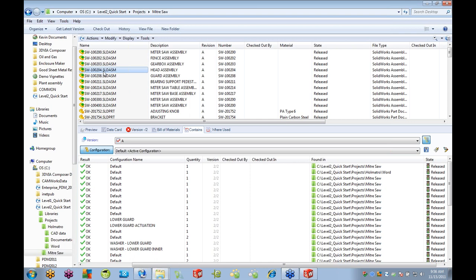Okay. What if you created it on the C drive of the server? If you created your local view on the C drive of the server, you're not going to gain any of the benefits of eliminating that check-in, check-out across the network, because when you check it out, it's just going to move it to the C drive of the server. But when you open it in SolidWorks, it's still going to have to go across the network to open it, and you're going to have that constant traffic.